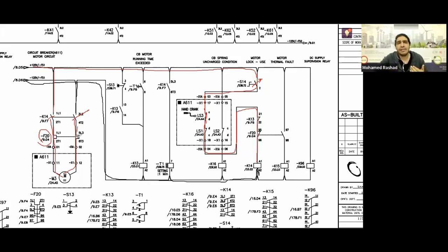Here, this part is like bimetal strips. You know those bimetal strips that are, if any of you have studied control or have definitely seen them in many sensors, where you have two different materials with different coefficients of thermal expansion. Therefore, when the current passes through, they expand. So when they expand, they might separate from each other completely, or they might expand upwards, and they start to do this, and they begin to push the system or push a cam.